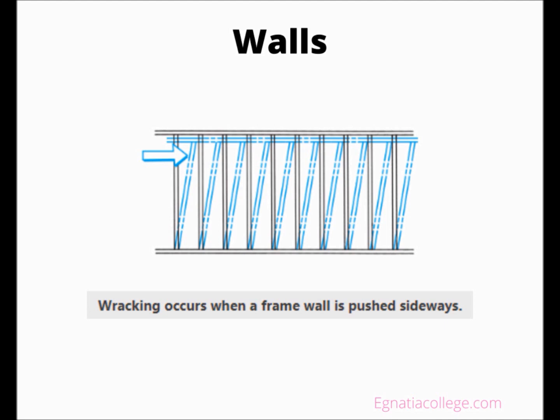Notice the garage door openings on the bottom floor. Since the shear panels cannot continue across those openings, the narrow wall on one side of the opening is paneled on each side and has heavy hold-downs tying it to the foundation. There is also shear transferred from floor 2 to the first-story wall. A critical design consideration is that the shear wall sections stack vertically, with upper-level shear walls occurring directly above the shear walls below.